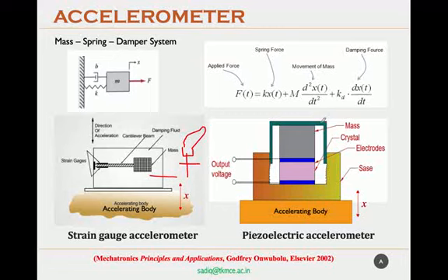Now, in the construction, the spring steel cap will be rotated such that it is tightened against the thread that is shown here. That means when you fix it to the base, the spring steel material will force this mass downwards, and a squeezing effect happens, and because of that the piezoelectric crystal will experience a compressive force. So in the assembly itself, this piezoelectric crystal is preloaded. Now let us see the working of this accelerometer.